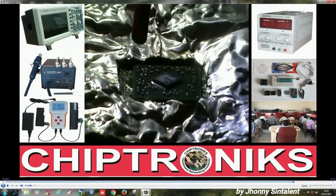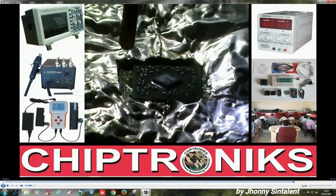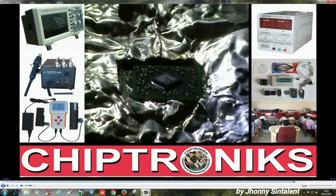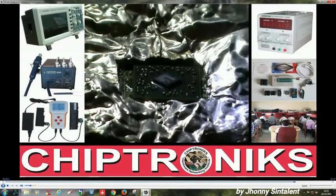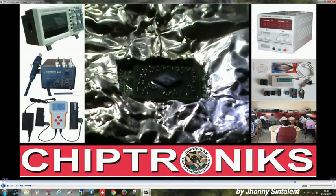And how to check alignment? We have to check alignment by seeing the borders from all the four sides, and all the borders should be visible. If all the four borders are visible, then we can think that this BGA chip has been correctly aligned. Now we'll start our BGA machine. We'll follow the same procedure to heat this, to resolder this BGA chip back to the PCB.